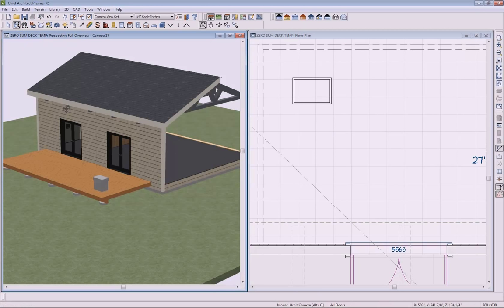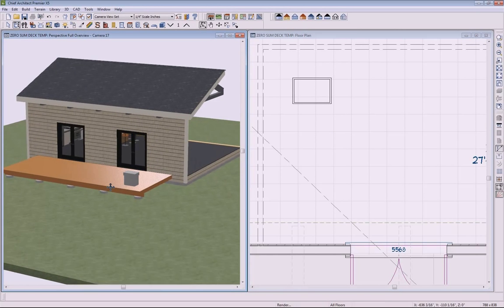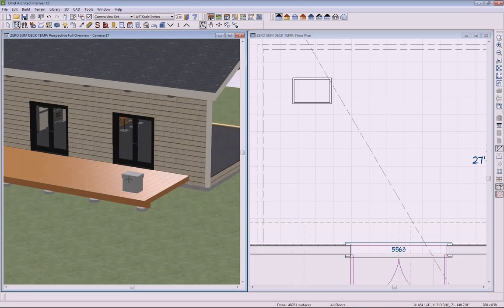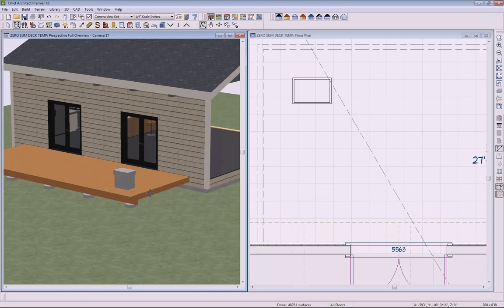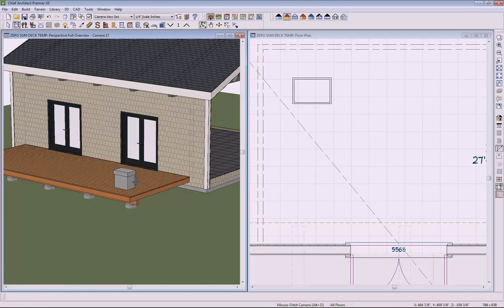on there. I'm just going to change my view here so you can see that a little bit. And by the way, we have a number of different rendering views. If you're having trouble seeing something in a render view, a little bit hard to see the definition there, we can switch this over to a vector view, and that adds the lines and makes the definition a little bit better. Okay.